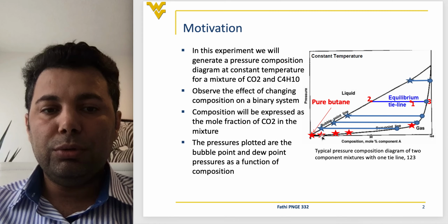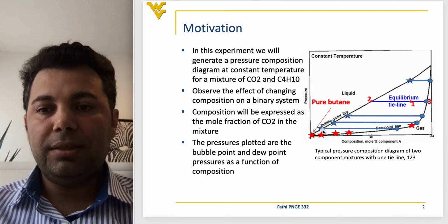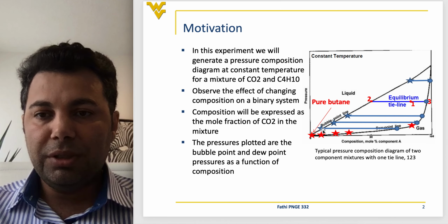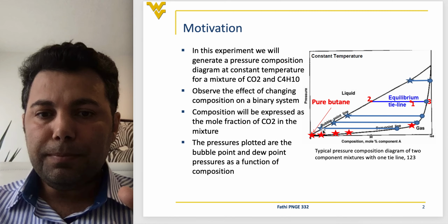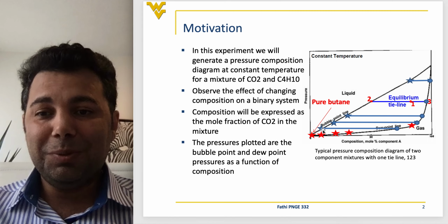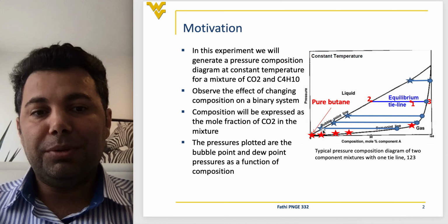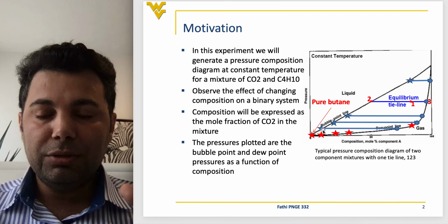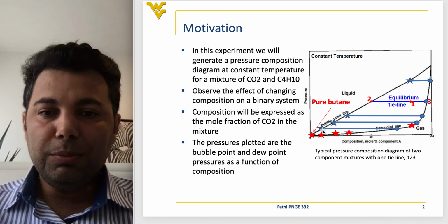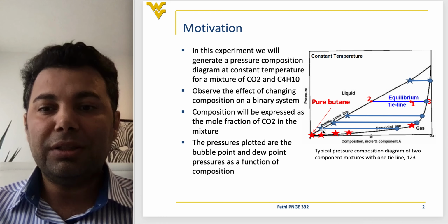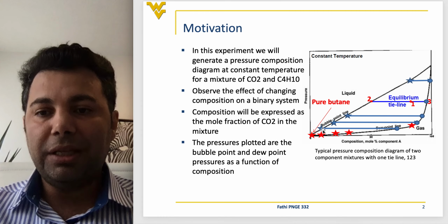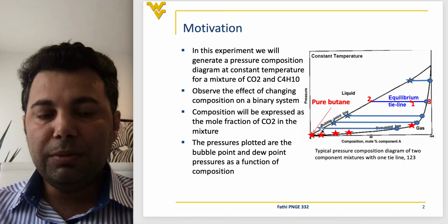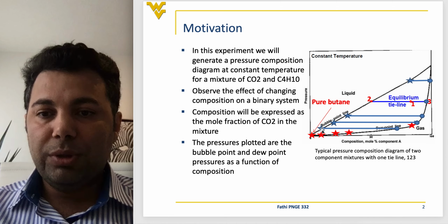So what we can do is find a bubble point. That's easy, because the liquid is incompressible or slightly compressible, so a small change in the volume will lead to a huge change in the pressure. Therefore, finding the bubble point is very easy. The liquid cannot expand that much. It expands a little bit and then it starts vaporizing, going to the gas phase. So we can find a bubble point, and when we find a bubble point, that's basically our saturated liquid.